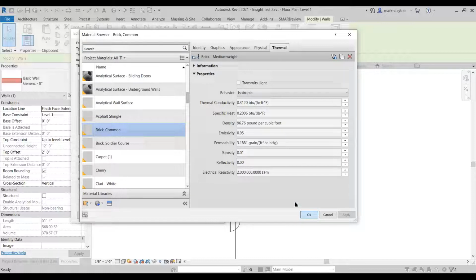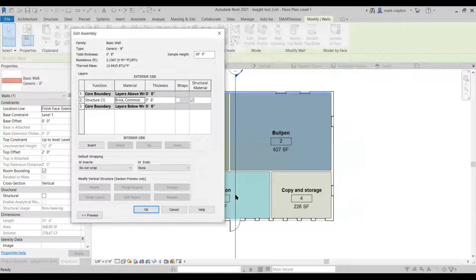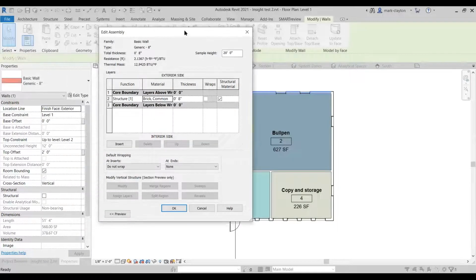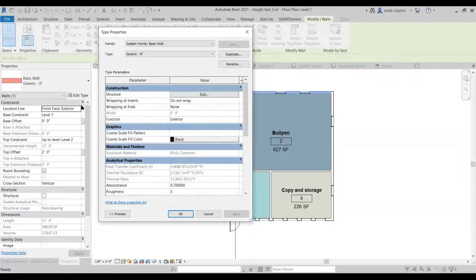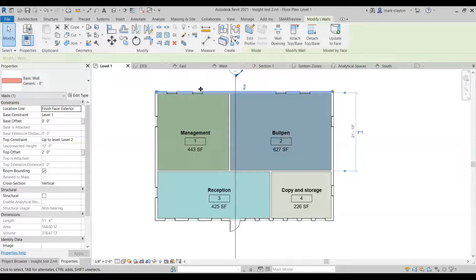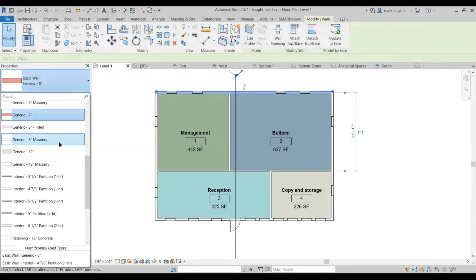Is there a way, after you've already built the item in Revit, to change the properties of it? Like if you have your wall settings a certain way and then you're like, oh, actually I want to use a different kind. Yeah, really easy. All I have to do is, see, I've got that wall selected. I can go and pick a different wall. Okay.